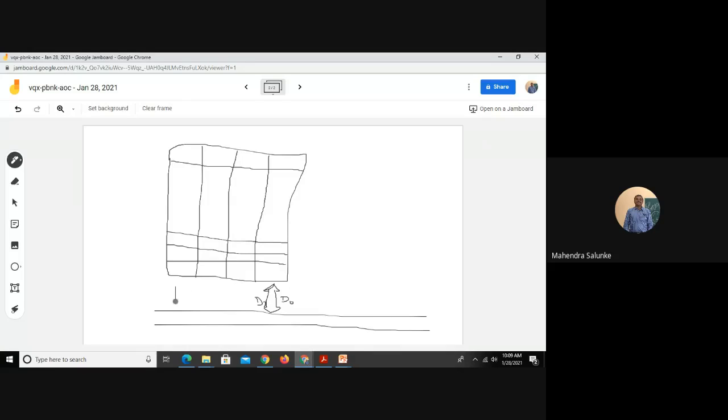And like that, you can see the bidirectional lines are here, and this is your D24 through D31, and this is the complete 32-bit data bus. This is how your physical interfacing is done with the memory bank. So we treat it as a complete memory bank, which may include ROM, RAM, whatever different memory chips we have.